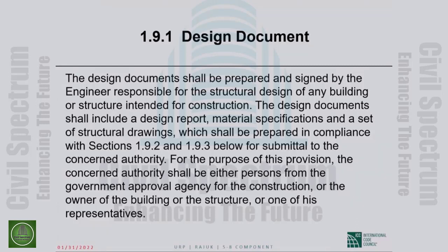The design documents shall include a design report, material specifications, and a set of structural drawings. Okay, so drawings and specs are always included in design documents, but BNBC specifically calls for a design report, which shall be prepared, together with the specs and the drawings, in compliance with 1.9.2 and 1.9.3 below for submittal to the concerned authority.